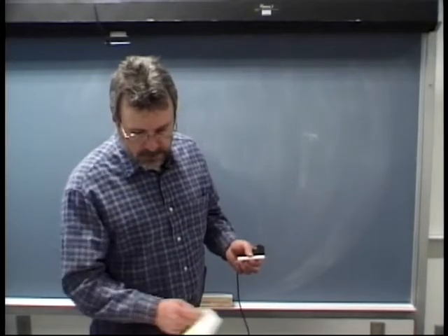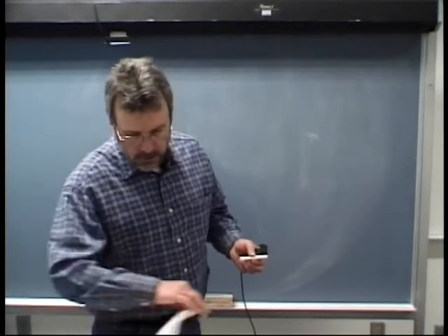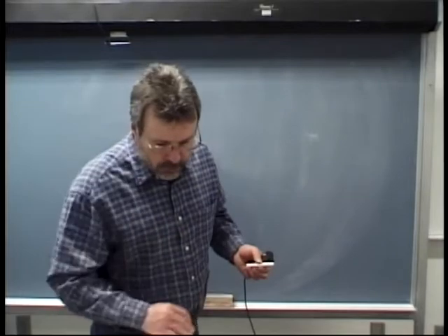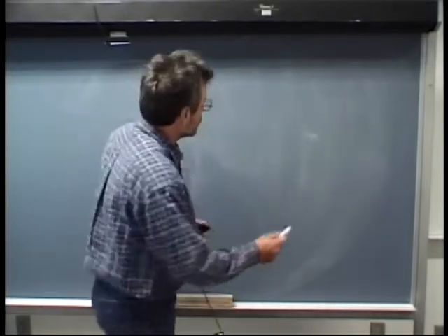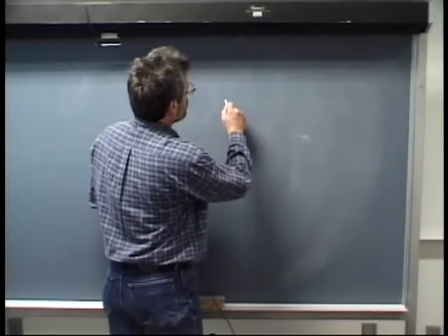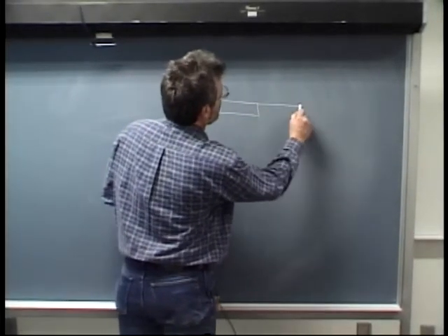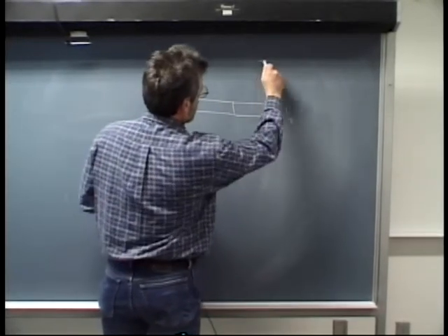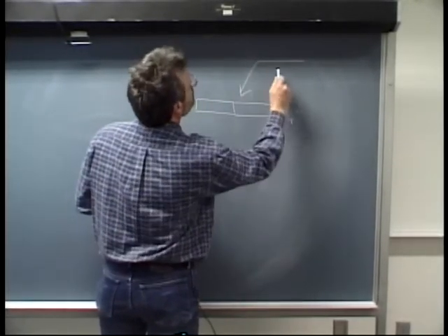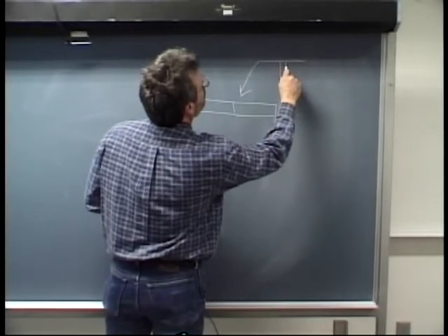So if that little crown there is colored in, you know it means melt through. They want you to melt all the way through the material. And of course, we're talking about real thin stuff here. Say you wanted to make a weld like this. Say this was 1/4 inch thick plate, and you had a welding symbol that came like this, and this would be a square groove.